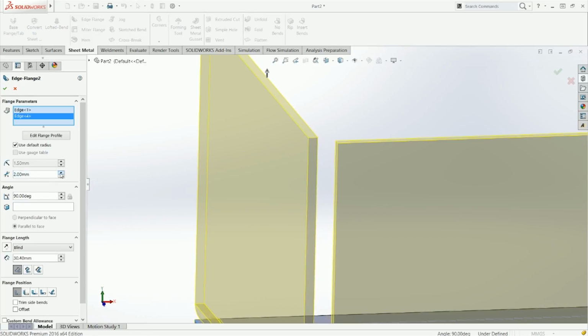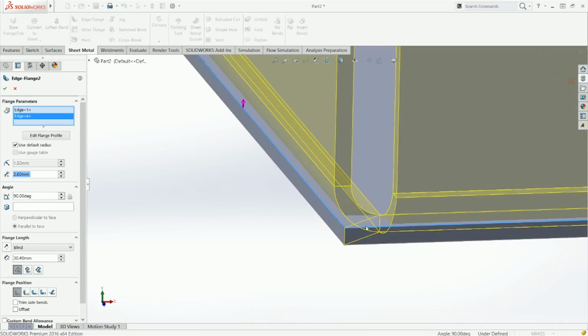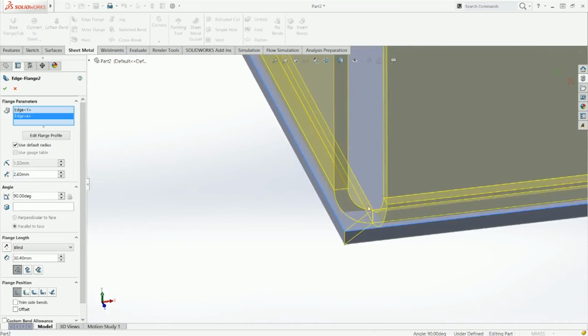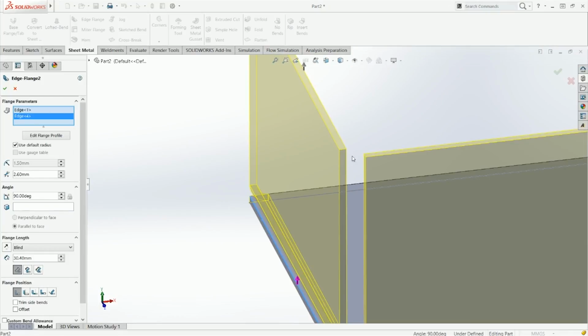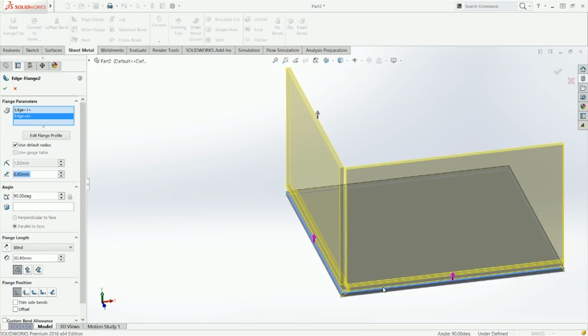When I extend this, you'll get a bigger gap, so that your welder can use a 2.6 millimeter wire and try to weld that. Obviously, that's too much. So that's how you define your weld gap, one way of defining your weld gap, at least.